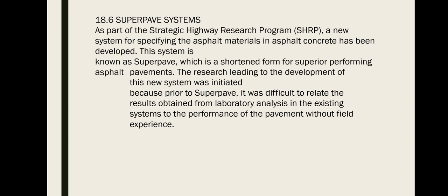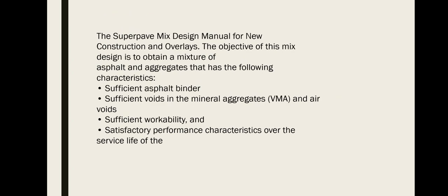Superpave systems. As a part of the Strategic Highway Research Program, or SHRP, a new system for specifying the asphalt materials in asphalt concrete has been developed. This system is known as Superpave, which is a shortened form of Superior Performing Asphalt Pavement. The research leading to the development of this new system was initiated because prior to Superpave, it was difficult to relate the results obtained from laboratory analysis to existing experience of pavement performance in the field.